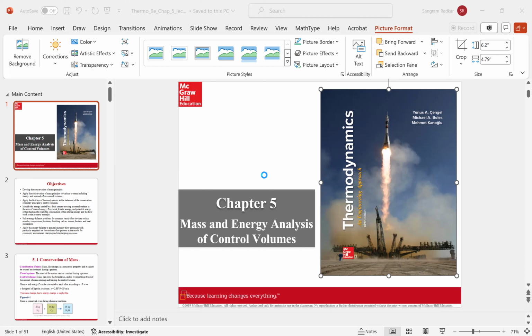What happens once you cross the sound barrier? Just to give you a crude example, that gas becomes like a solid, like a sluggish solid. So when you have a solid coming out through a converging nozzle, it does not increase the velocity. In fact, it decreases the velocity because one particle impedes the motion of the other particle. That's why at supersonic speeds, the nozzles are diverging. At subsonic speeds, nozzles are converging.